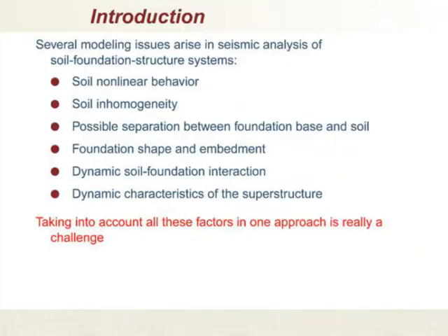And what I'm trying to present today is a new modeling technique that tries to account for some of the challenges in modeling, such as soil nonlinear behavior, soil inhomogeneity, possible separation between foundation base and soil, foundation shape and embedment, dynamic soil foundation interaction, as well as the dynamic characteristics of the structure itself. As you may know, accounting for all these factors in one computational technique is quite a challenge.